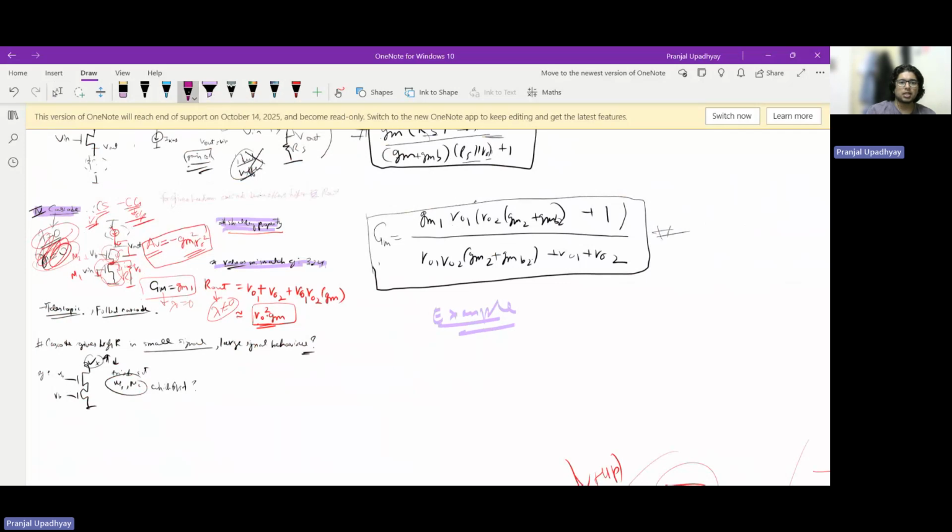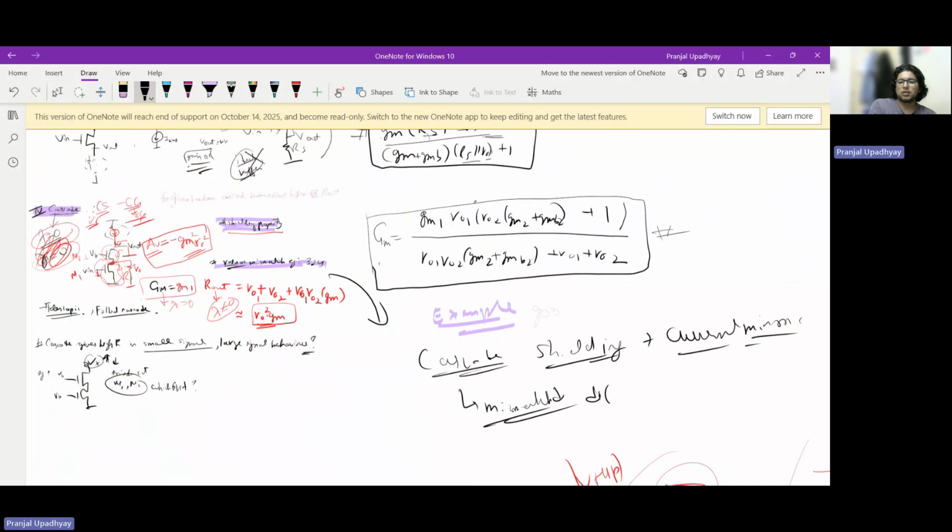As for why a cascode device is great for shielding voltage at certain nodes, which finds its application in current mirrors, and also reduces mismatch, especially when we apply it in differential applications, that's something we'll discuss later.